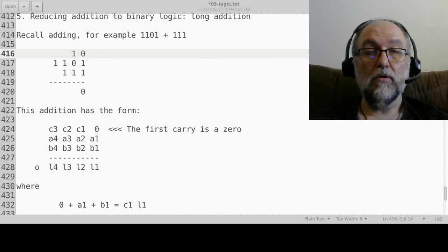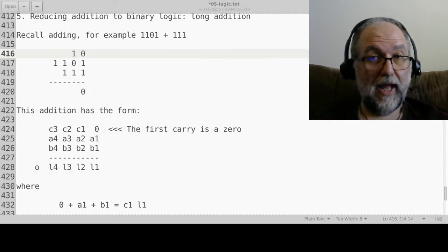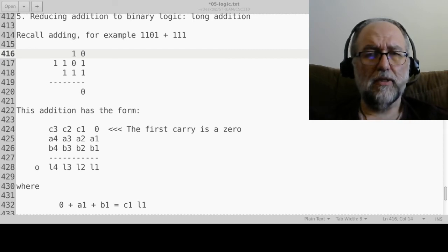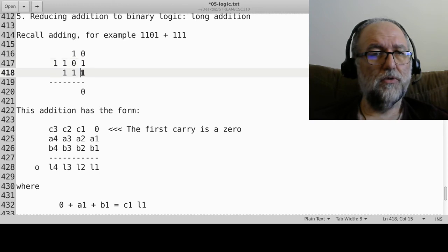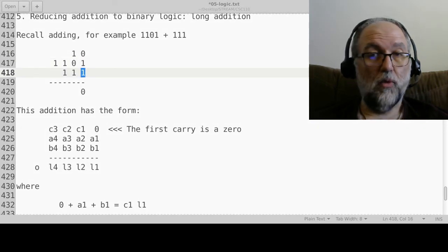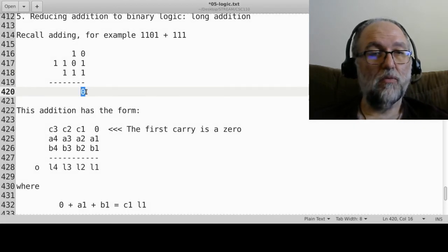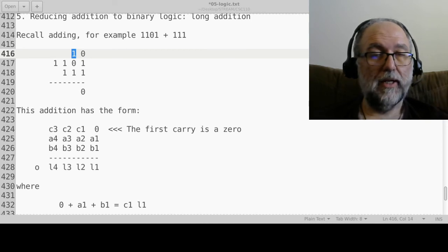And that first column was a result of 3-bit addition. Do we have a machine to do 3-bit addition? Yes. What comes out of that machine? 3 numbers go in. Here they are, 1, 2, 3. Those are the 3 switches you saw a minute ago at logic.ly. And 2 numbers come out: a least significant figure, which is part of the answer, and a carry. And where does the carry go? The carry goes into the next column.